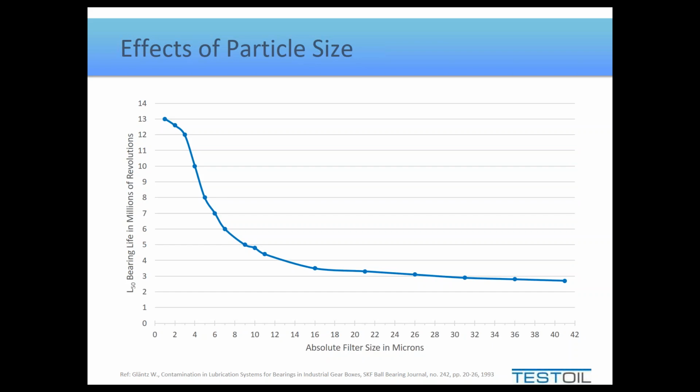But one of the things I always say about looking at studies is there are 3 words I try and keep in mind when I view any of this type of information. And those 3 words are practical, feasible, and economical. Is it practical to move from 40 micron to 1 micron? Well, there will be some logistics involved in that because a 1 micron filter will have to be sized completely differently than a 40 micron filter due to backflow pressures and overall flow rate through the filter. Is it feasible? Do I even have the real estate to be able to accomplish this? And economical. If I got a 4 times life extension on the bearing, would that be cost beneficial compared to what I had to spend upgrading the filtration system?